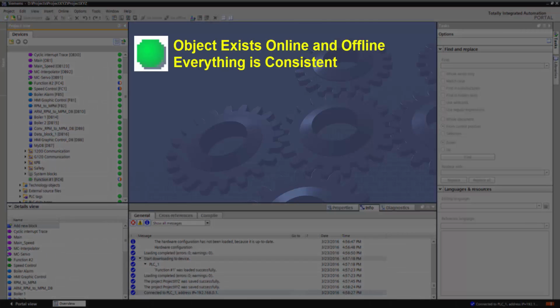The green icon indicates that everything is okay with that object, meaning what we have in the offline project perfectly matches what is running in the PLC. The icon with the blue half circle that is not filled in and the orange half circle that is filled in means that this object does not exist in our offline project, but it's somehow in the PLC.